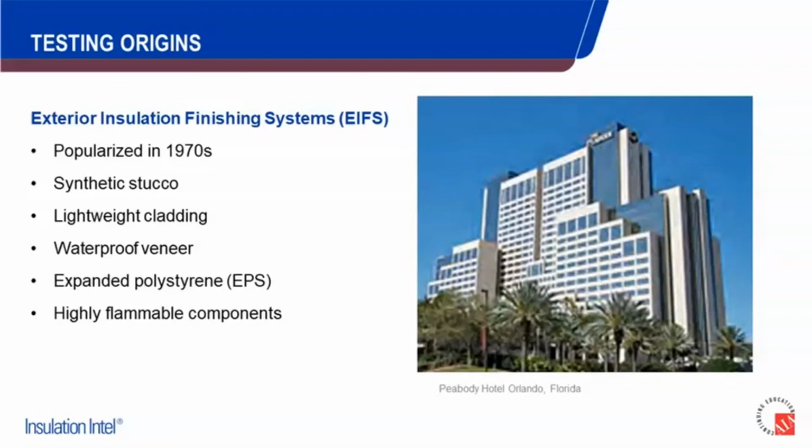One of the first material systems that came out to address this, and that was fairly heavily publicized, was the EIFS system, which is essentially a synthetic stucco. I like to think most of the people on the call are at least mildly familiar with it. It's a very lightweight version of stucco, essentially a mastic, acrylic-based system versus an actual masonry-type system.